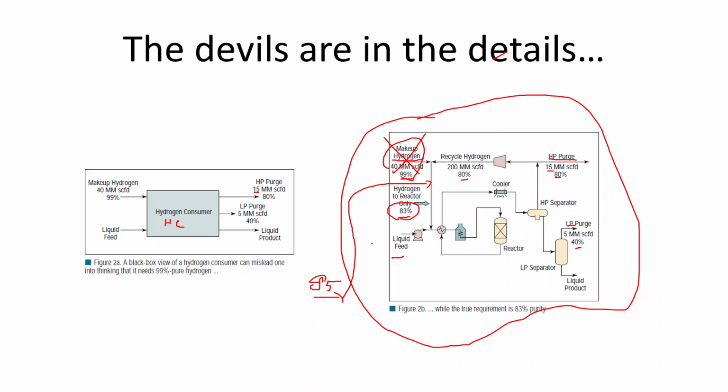If this is enough, because from the hydrogen perspective, that hydrogen concentration and the flow rate may be sufficient, but in terms of the other impurities which we don't know, that is something we have to dig deeper into. If all the other components are not an issue for this catalyst in particular, then you can propose this as one of the modifications. So then you will save this amount of money, right? It's something that we can think about, and use as a base for a discussion going forward.